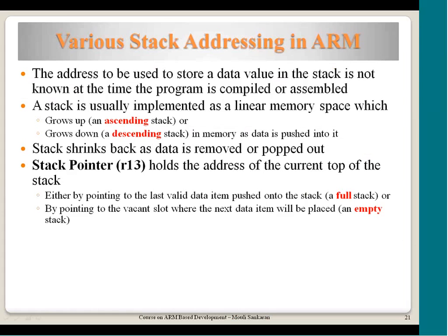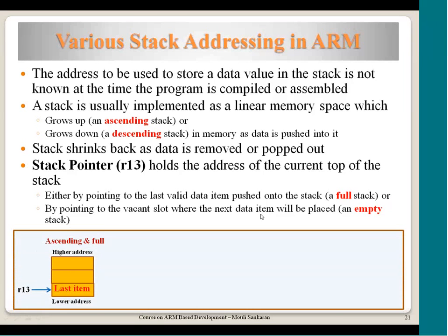Now, as I told you, R13 is one of the registers used for pointing at the location which is the top of the stack. There are two options available. Either it can point to a place where a value is already stored in the stack, or it could point at a place where empty space is available. So I'll give you an example here. This is called ascending and full.